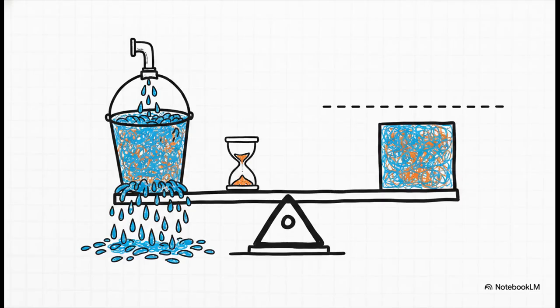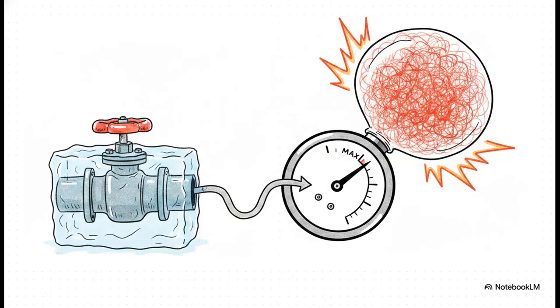So the crucial point here is that we clearly need something else to fix that permanent gap. Enter the I, the integral term. We like to call this the past. The integral term exists to eliminate that steady-state offset, and it does this by accumulating the error over time. It is pretty brilliant. It looks at how long the system has been stuck away from the set point. Even if the error is tiny, just a fraction of a degree, if it sits there for a long time, this integral sum just grows and grows. It eventually forces the controller to apply that little bit of extra power needed to push the system exactly onto the set point. But yeah, another flaw.